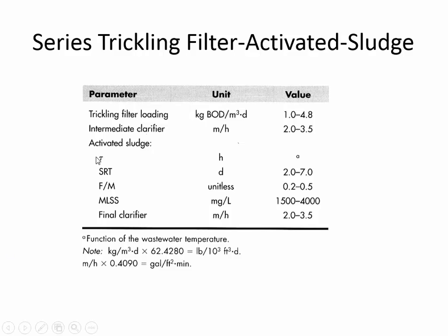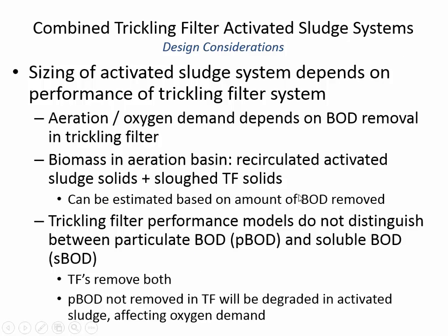So this is showing some of the typical design parameters for trickling filter activated sludge in terms of the solids retention time of 2 to 7 days that we were looking at before, food to microorganism ratio, suspended solids concentration, and so on.